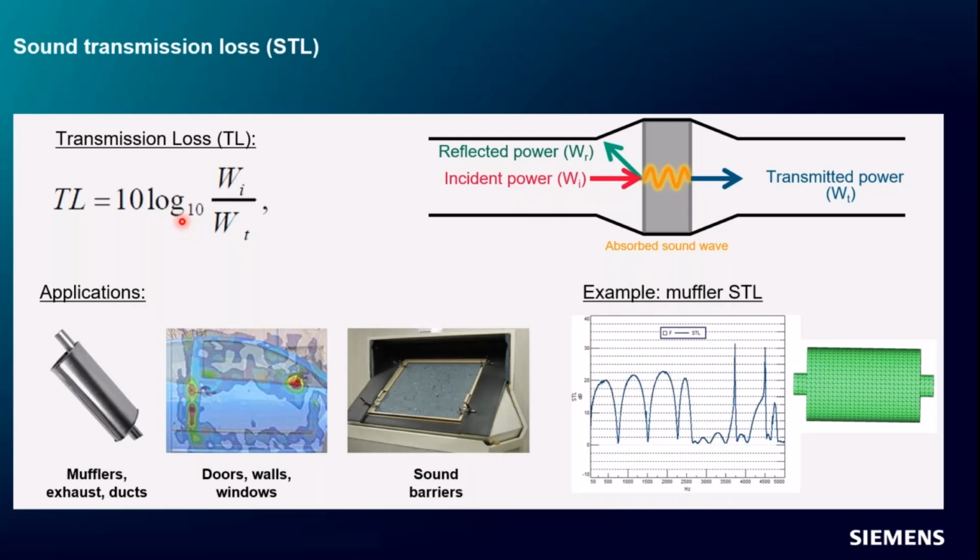Now, when we look at sound transmission loss, for example, this simple expansion can here, it's really nothing but a radius change. You have an inlet pipe, and then it gets bigger, and then it goes back to the outlet diameter. And you look at the sound transmission loss, and again, higher is better on this chart. And versus frequency, you see there are some places where it does really well, 20 dB of sound transmission loss. You see that sort of repeat. But you see these drops in the sound transmission loss, right?